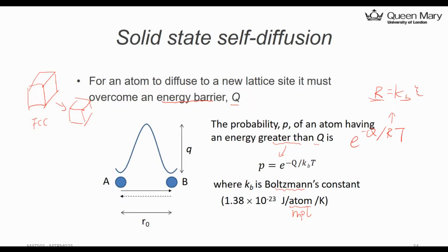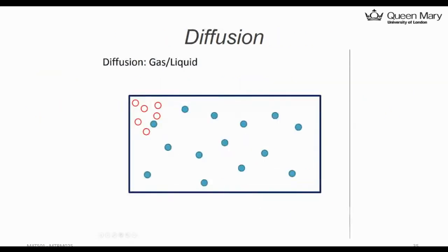It's basically a diffusion problem, but this quantifies a probability. Q is the material constant. If you raise the temperature high enough, RT will be essentially larger than Q, so your probability will then equal 1, a very high probability to force your atom to travel from one lattice to another lattice. That's how diffusion happens. So that's the equation for it. So let's watch a video to understand the diffusion better.